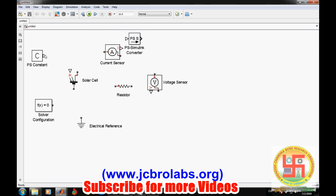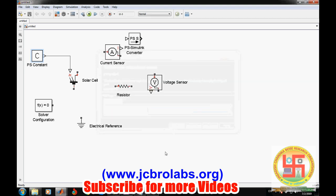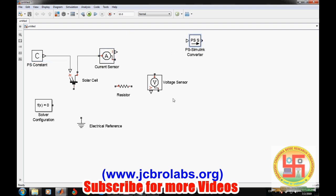Yep. Now let's connect. We connect the irradiance to the solar cell. Okay, and if we double click on it, we can put a value of the irradiance. So let's say 1000 watt per meter square. Now it should go to the current sensor.